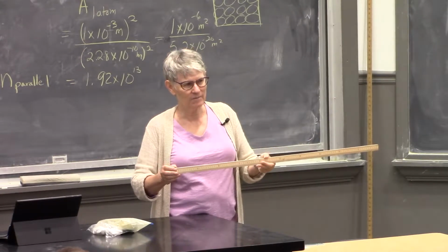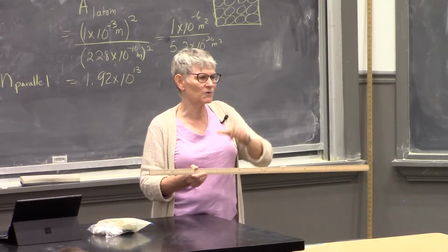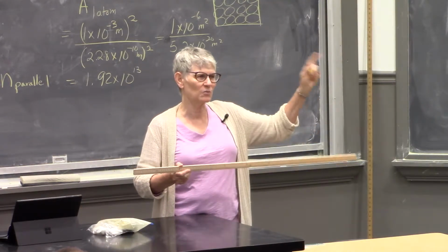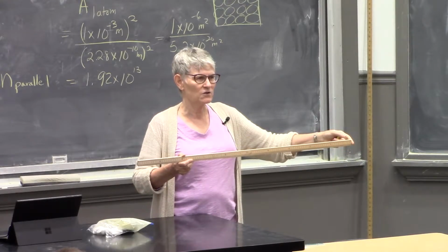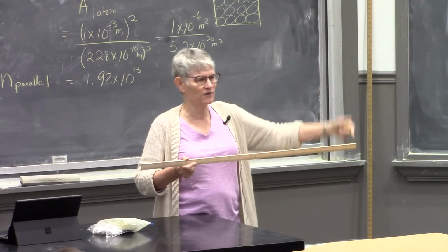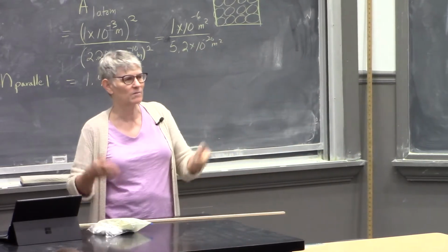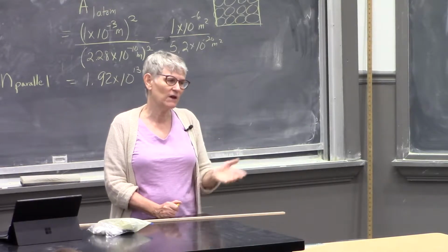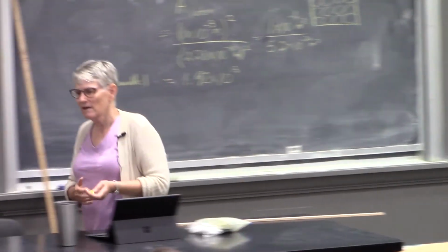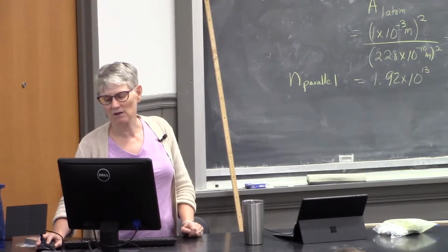And if you tap it with a hammer here and start a computer sensor going, like your computer interface upstairs that's just connected to the microphone, just time it until the microphone hears something, so you can actually measure it that way, and you can get the number that way. There are more accurate methods. So we can do that. Okay, so this worked for aluminum. Let's see if it works for a different material.